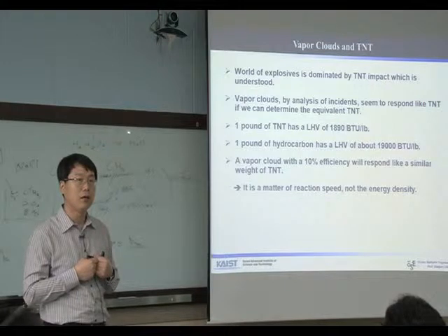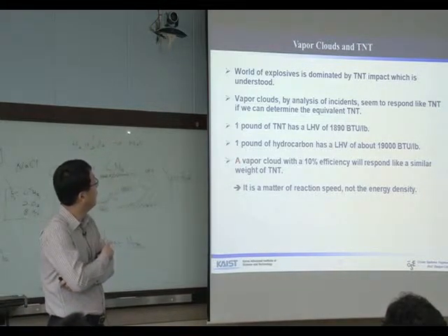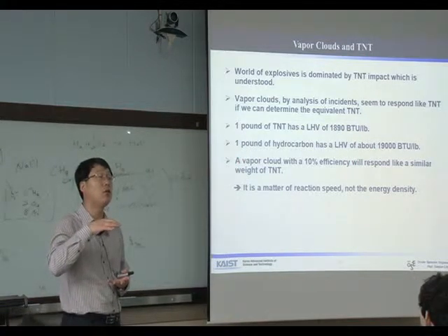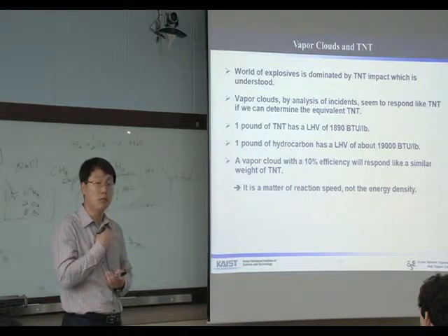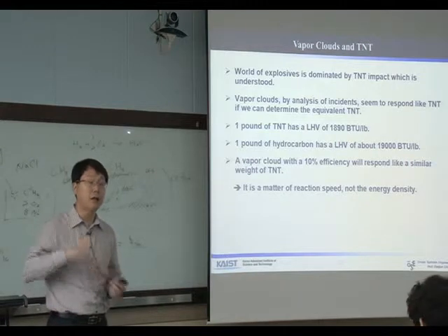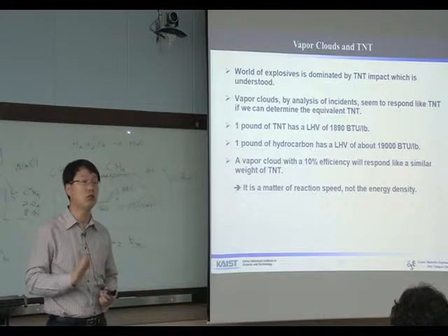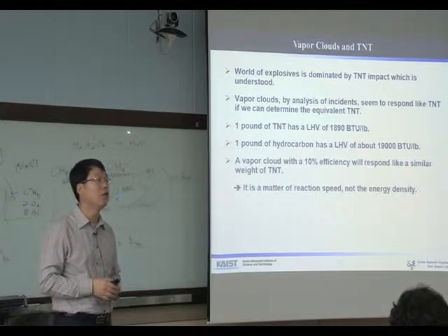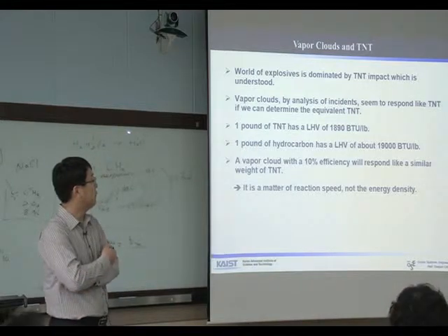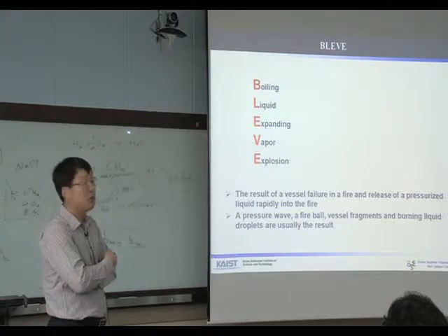Okay? The explosion overpressure we can observe is not governed by the energy itself. The contained reaction energy is important, but the speed of reaction is more important than the contained energy itself. This one is important.